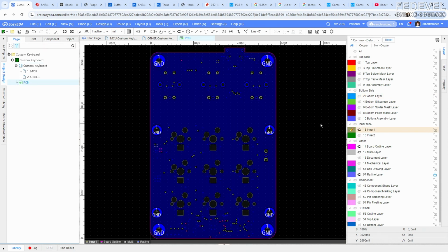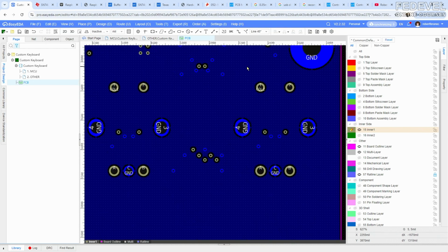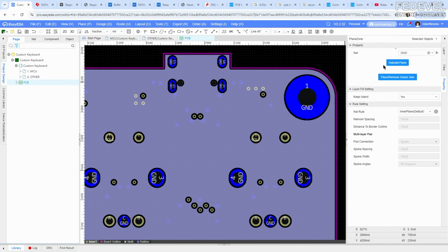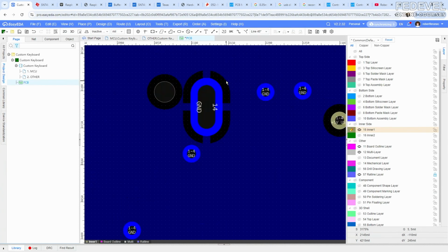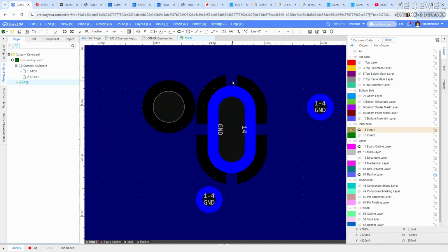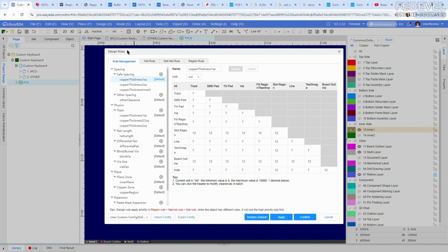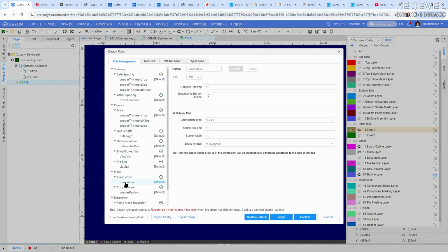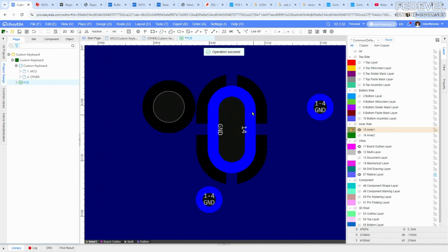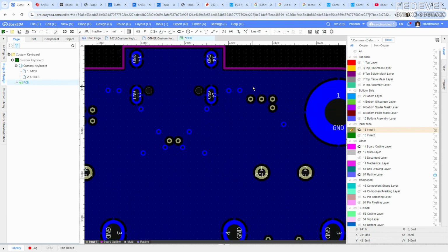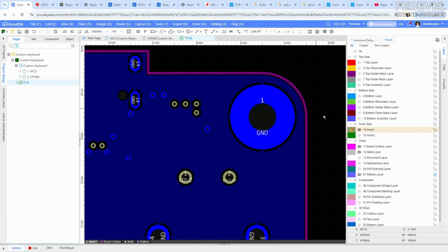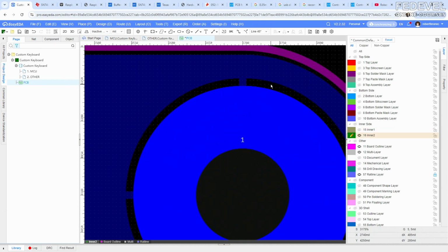Now go on these inner layers and double check how these ground planes are connected to ground pins. Like this. This is called thermal relief, and we would like to make it maybe a little bit wider. So go into these design rules and change this width to be 15. We use this thermal relief so it is easier to solder the pins.